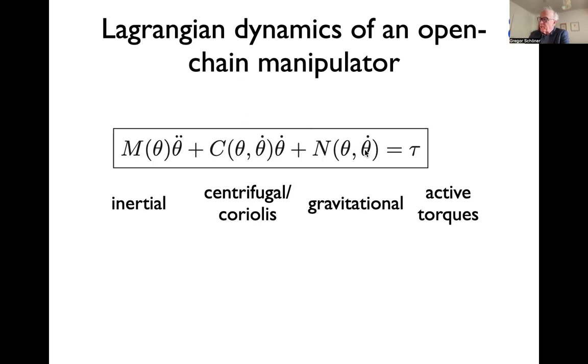The gravitational term is more trivial, right? If you change your configuration to gravity, there are different angular momenta created by different torques essentially generated by the gravitational angle on your joint, and that can be treated trivially. The generalization is, the Lagrange formulation is really for conservative systems without any change in energy. But if you insert energy, it becomes an open system. You have an engine, a motor there that burns energy, and you can model that by figuring out at which level this enters. So if you have that formulation, then these would be what is conventionally called a joint torque.